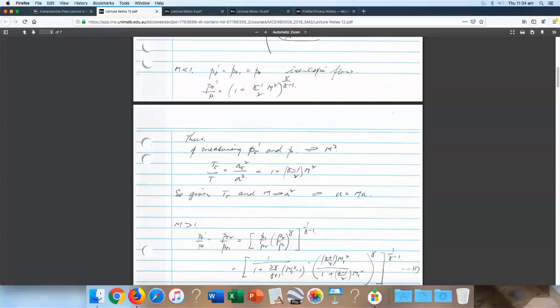And I have a complicated flow inside the rocket nozzle. The simplest idea would be that it's a normal shock, but it may not be. It may be much more complicated. There's boundary layers that separate, and the flow gets turned ahead of the shock wave, and there's complications. So if I have overexpanded flow, then this assumption is not really true.